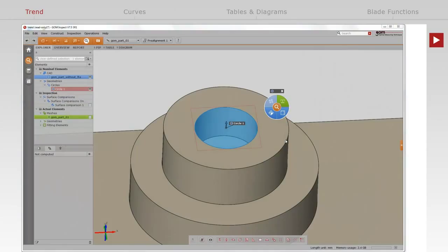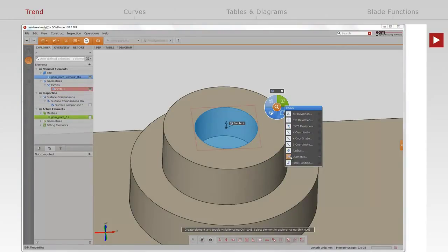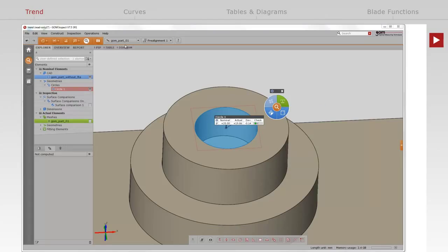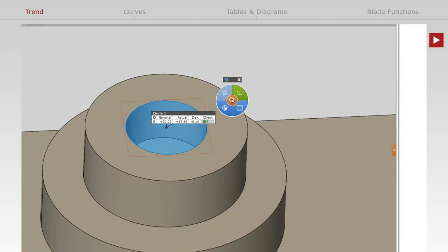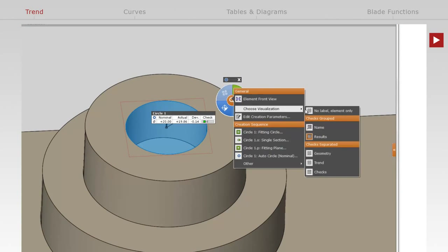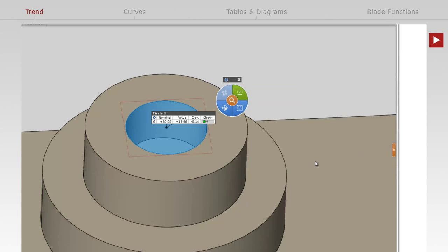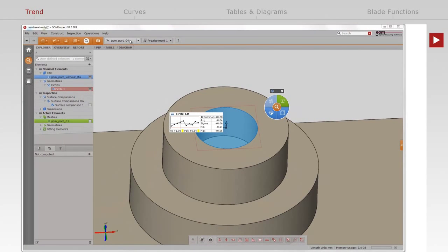It is also possible to extend your inspection at any point, such as the inspection of a circle regarding its diameter. Any inspection will then be recalculated for all stages automatically. You can now change the stages and get the results displayed immediately. In addition, you may change the label template over the Edit button of iInspect in order to display tendencies.